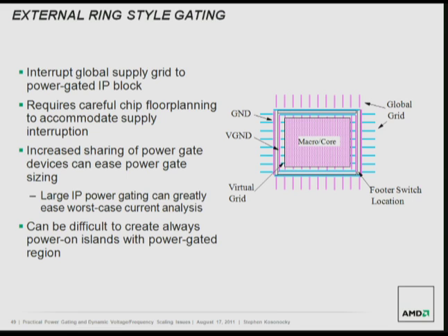But by doing this ring style, it does make things a lot easier on the design side, because now the CPU design really doesn't have to know anything about power gating. You just do it as normal, and then you just plop it in and put the ring around that. So things like timing and verification become much, much easier for the CPU team.